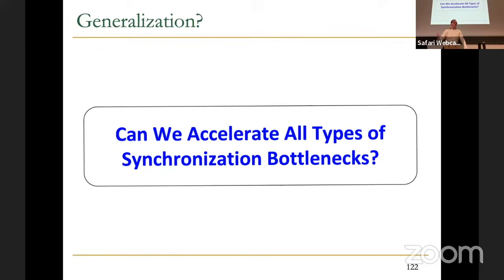Normally the way general purpose design happens is you have a target set of workloads, which is quite diverse. You run traces, for example, you collect traces from your customers, you add your traces that are from benchmarks. For example, there could be easily thousands of traces in your trace set or workload set. And you do some design space exploration based on those traces. You run all of those traces and you try to figure out what kind of performance, what kind of energy you get. And that's very intensive to begin with, right? You need to simulate things. You cannot really run them on real hardware.